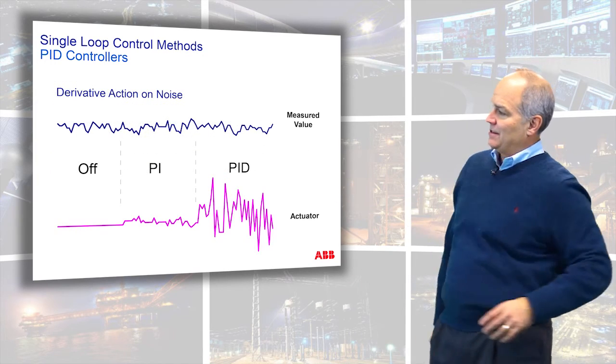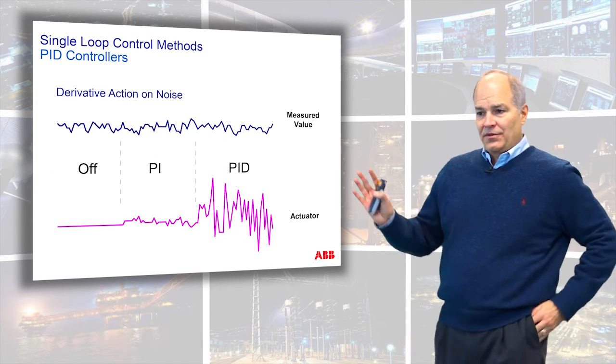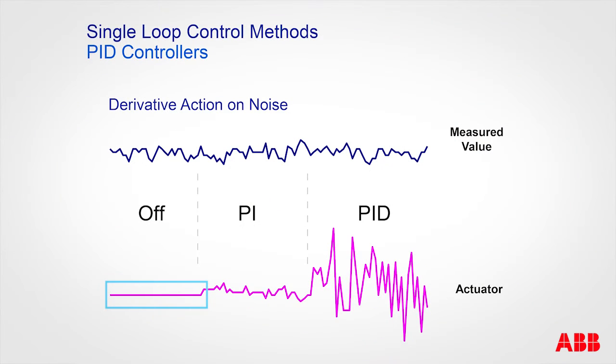This is showing a simulated case with 3 different phases. In the first, off control, the actuator's not moving, so the measurement's just wiggling along. So I kind of got a noise signature. Then I put the PI algorithm on, and you can see it sort of jerking around, and I get a little bit tighter. There's a whole bunch of control theory in that one statement: you want the noise, you want the signal to be removed. So that's what a PI algorithm does.